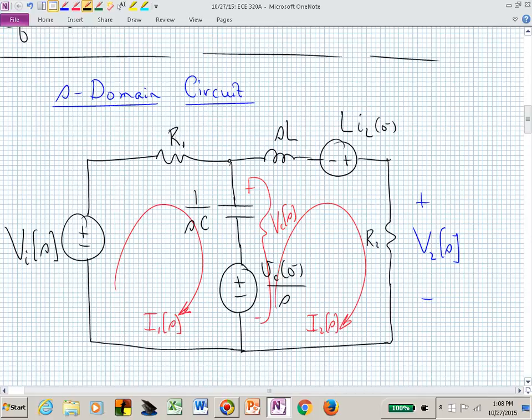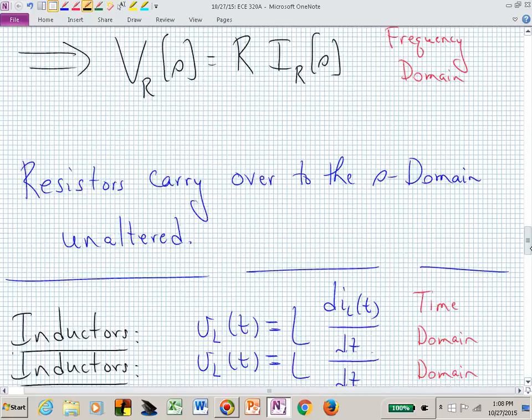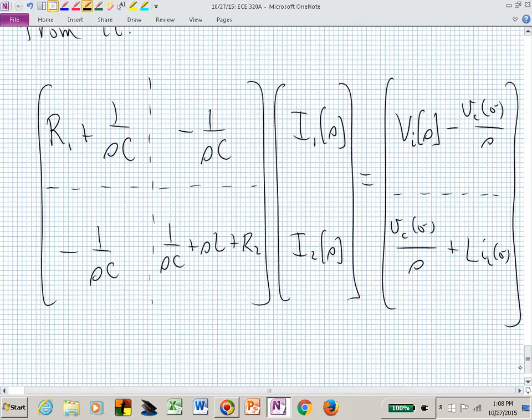But now when you come to the impedance of the capacitor, you're wanting a positive drop from top to bottom. And the way that you've sketched I1 and I2, I1 encourages that drop and I2 doesn't. So the net current going down in that capacitor is I1 minus I2, so that any piece of that expression that involves I sub 2 has a minus sign, and that's where that minus sign is coming from. Because if you multiply this out, you should get that very first mesh equation.